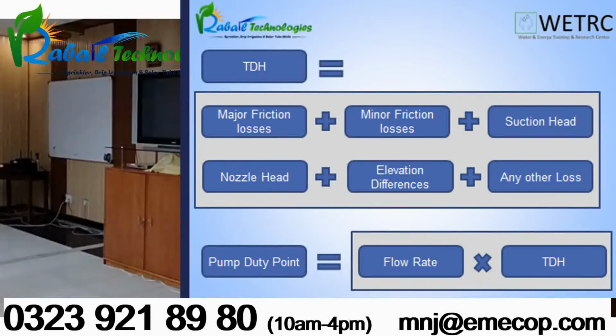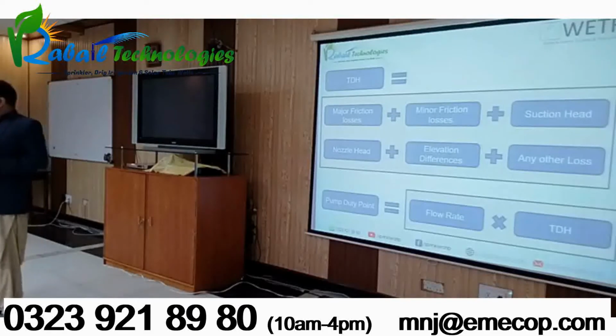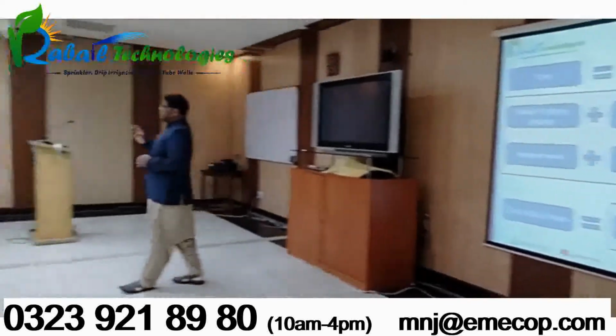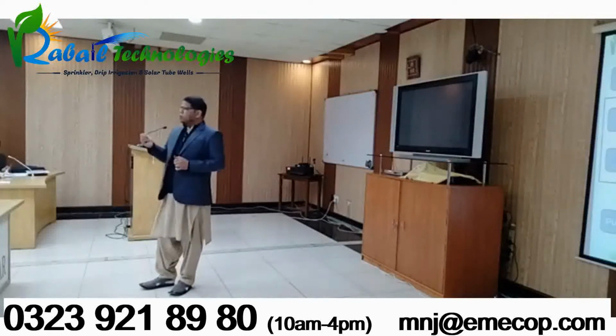So we have the formula to calculate these minor losses one by one, but being a practical person, being in the field, and as I mentioned at the start of the training, I'm not here to teach you the theories, I just want to give you the practical approach, the concept of the system. So we take minor losses as 20% of the major losses. That's simple. If major friction losses are 10 meters, how much will the minor losses be? 2 meters.